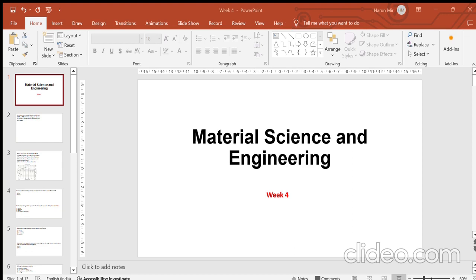of eutectic alpha. So the first thing you have to know is that we are below the eutectic temperature. So we are less than the eutectic temperature, right? Point two is that we have constituents of two things. One is the eutectic mixture and another is primary alpha.